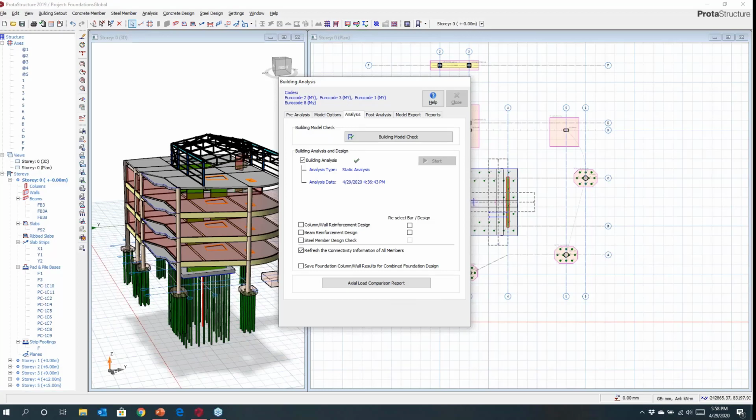Now what we don't do at this point is build out a soil model for the piles. So we're not putting all the piles in and providing lateral springs at this point. That may be a future enhancement that we look to introduce, where we start to create a more sophisticated substructure model. But at this point, you can just combine these two together and you can get a feel for the global behavior of the structure when the foundations are considered together with the superstructure.